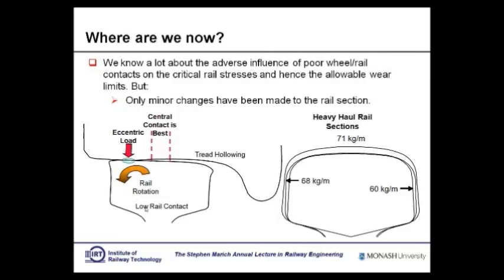One of the odd things is that you may think about a rail section. It's sort of a bastardized I-beam structurally. It's a real bad I-beam actually, because it has a foot, it has a very thin web, and it has a big head. Now, I-beams, of course, structurally are wonderful if you only apply vertical loads to them. If you start to apply eccentric loads, I-beams don't work out too well.